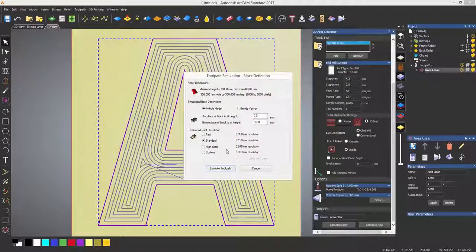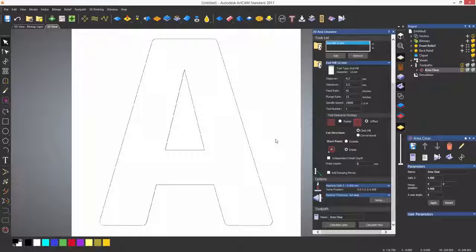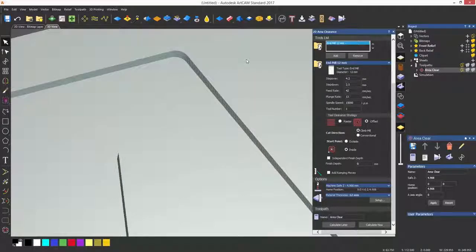The corners for the centre island are fine because the tool is rolling around them and creating a sharp corner, but the internal corners, the tool will not be able to get right in there because of the radius of the tool. So there is a 6mm radius in those corners, as can be seen on the simulation. This will never be a completely sharp corner because I need to use a diameter tool to machine it, but